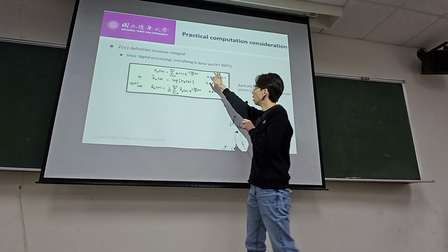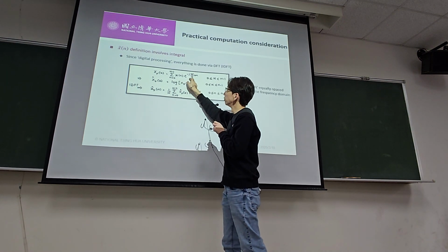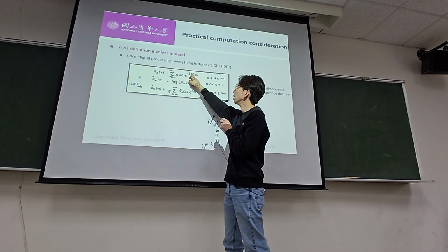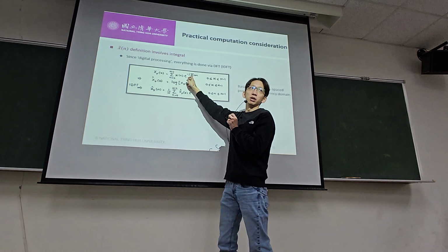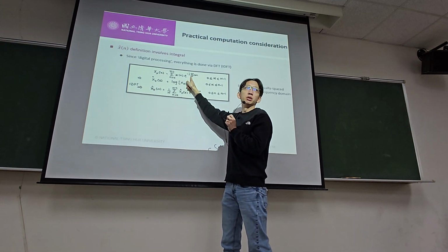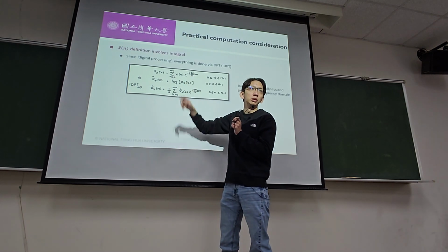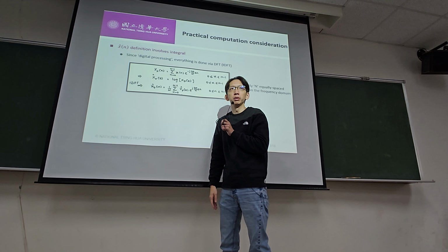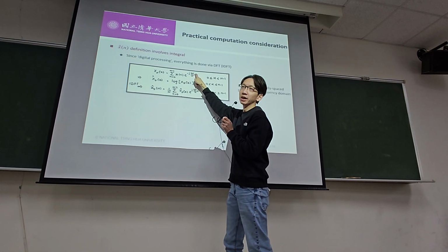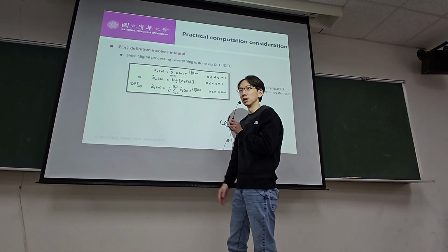So whatever you're doing, you do a forward transform where, instead of e to the minus j omega, we say omega is split into 2 pi k over N, so that you sample around the unit circle, splitting the 2 pi unit circle into N equal points. That's how our computer operationally performs the Fourier transform. We don't use the actual omega here; we use 2 pi divided by N. It's the implementation of the DFT using this kind of operation.